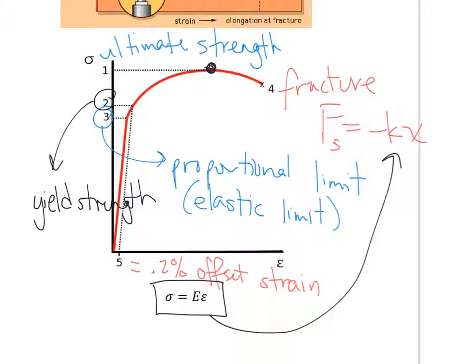So, certain materials are very malleable, and you get a lot of plastic range, where it hits that yield stress, and it starts to stretch more and more and more. This was not malleable. It broke at one instant. It didn't stretch at all. Take a look. It continued according to Hooke's law, and then it just snapped. It didn't ever enter that range where it started to get really stretched and then snap. So this material does not have the same properties as a material like metal, for example.